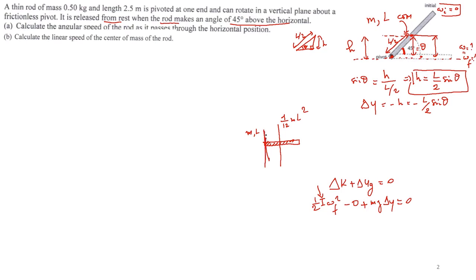Parallel axis theorem. Okay, so the new moment of inertia is the old moment of inertia, 1/12 of mL squared, plus mh squared, but h here will be L divided by 2. And we did this many times. If you do it, you will find 1/3 of mL squared. Bottom line, when the axis of rotation is passing through the middle, it's 1/12 of mL squared. When it's passing through one extremity of my rod, it will be 1/3 of mL squared. And we already demonstrated this in class.